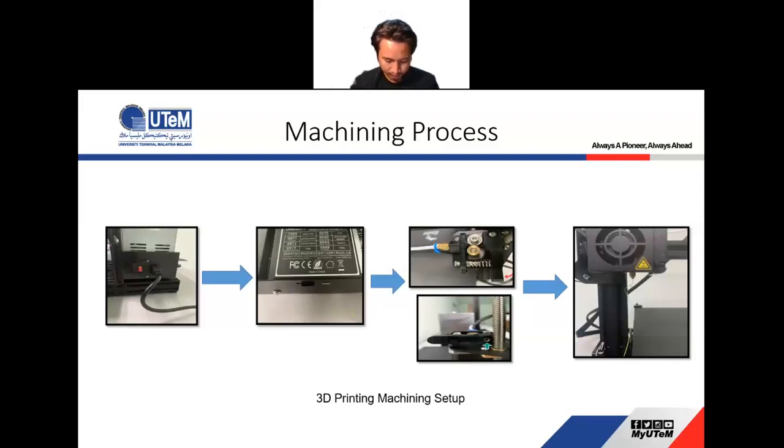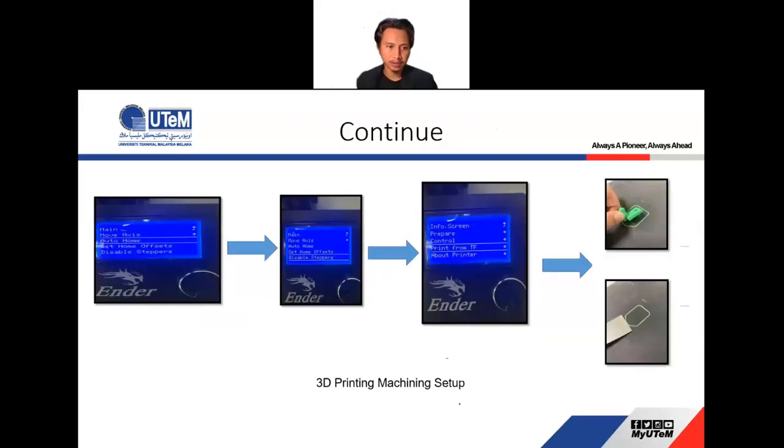And then, after we already heat the filament, the old filament will push out from the nozzle, as you can see in the last picture. Wait until the new filament flows out of the nozzle and clear the extruded filament from the nozzle. And then the next step is to